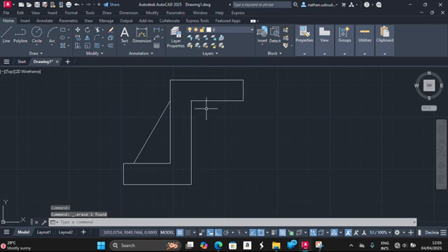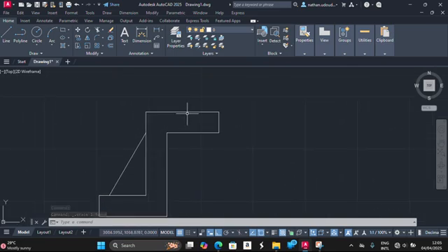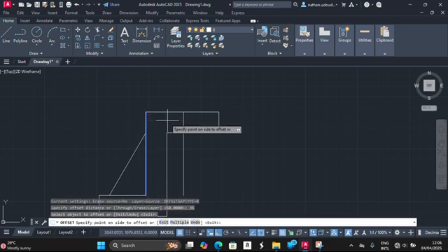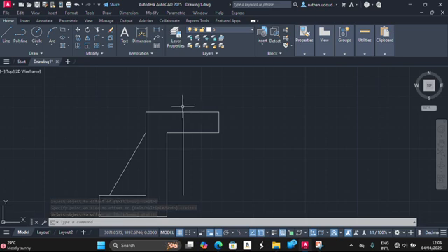So now the upper part, this curved part, from here to here, let's offset it by 36. So offset O, enter, 36, and then you have it from here to this point. So right click and then left click on enter. So now this gives us the midpoint for that cylindrical feature.